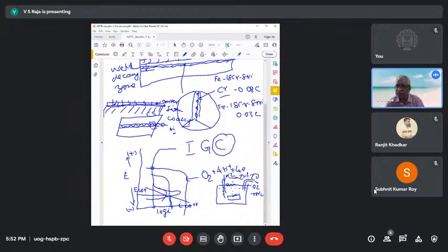This is sometimes, people call it a misnomer. They call it a rust converter. Rust does not convert into metal. The rust is converted into a coating actually, with epoxy. So when you do a phosphate coating, the rust is converted into a phosphate coating along with a resin and gives you better performance. So you can have a standalone hard manganese phosphate coating that gives you this.